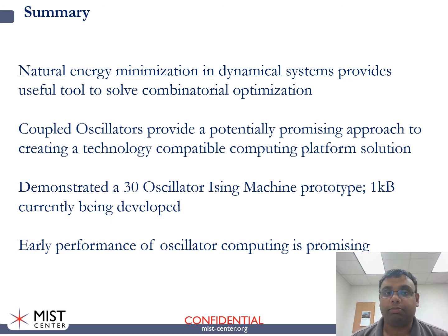And so, in summary, a few takeaway points are that natural energy minimization in dynamical systems provides a useful tool and approach to solve combinatorial optimization. In our case, we've explored coupled oscillator-based dynamical systems to implement this approach, and the reason for that is they provide a low power, energy efficient hardware substrate for doing this. Our initial demonstration with 30 oscillators has provided preliminary promising results, and we hope to extend that to larger systems, including a 1 kilobit oscillator Ising machine. And the early performance of this oscillator-based computing is promising.